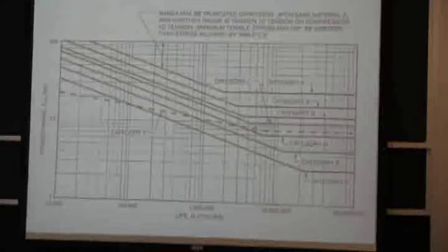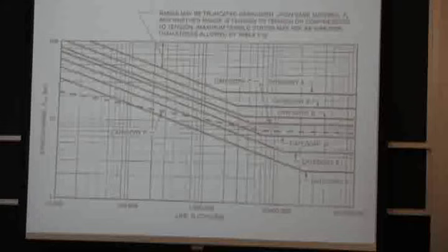If this is again this chair that just a couple of times somebody is really going to proof load test, then sometimes you can get away without wondering about it. So vibration is a good example of situations where the welds will give up. It happens on bridges. A lot of bridges, you have to design the welds in special ways.